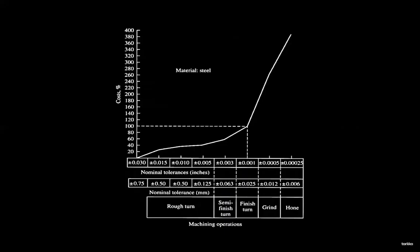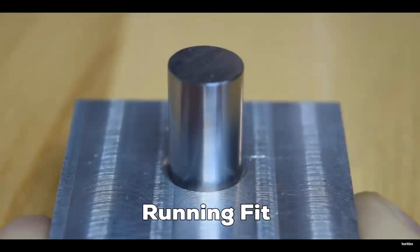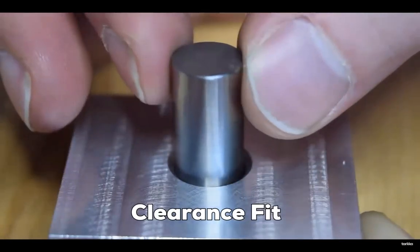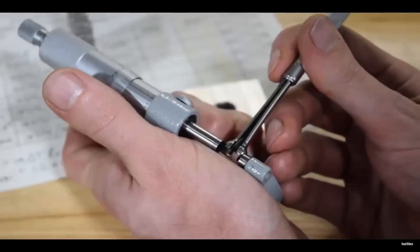A very common mistake that new engineers make is selecting tolerances that are far tighter than necessary. As the tolerances become tighter, the cost to manufacture the part grows exponentially. So how tight of a tolerance do you need? Tolerances typically come into play when designing fits. In some cases, you might want components to slip together easily, but not have a lot of perceptible play. In other cases, lots of relative movement is okay. You might even need to have two components come together permanently and not come apart. These different cases are called fits.